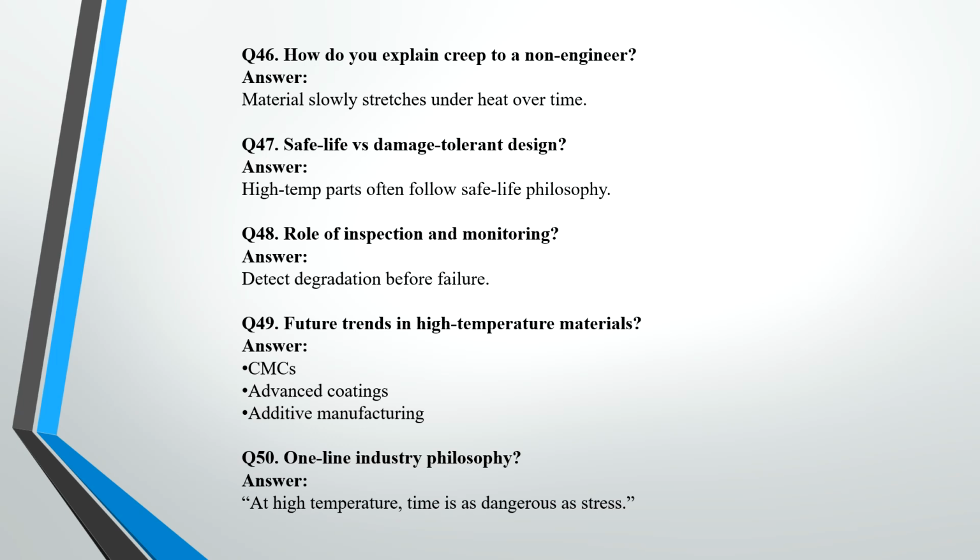What is safe life versus damage tolerant design? A high temperature part often follows the safe life philosophy. What is the role of inspection and monitoring? It detects degradation before failure. Future trends in high temperature materials: in future, we can use CMCs, ceramic matrix composites, advanced coatings, and additive manufacturing. These are the future trends in high temperature materials.